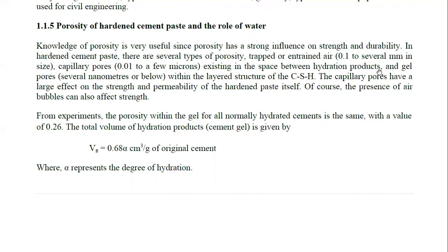So the capillary pores have a large effect on the strength and the permeability of hardened paste itself. The presence of air bubbles can also affect strength. From experiment, the porosity within the gel for all normally hydrated cement is the same, with a value of 0.26. So this value is experimentally proved.